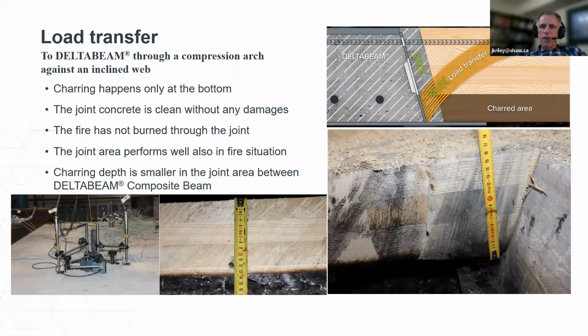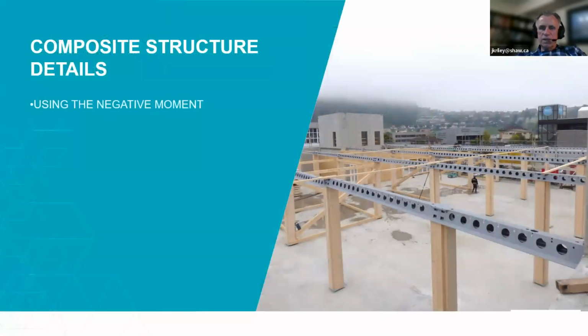Okay, let's move away from fire and let's go back to some of the design notes. So as I mentioned earlier on, we use Gerber connections, and a lot of the connections are done across the tops of the beams, or tops of the columns, not the tops of the beams. Well, actually, top of the beam, come to think of it. So what you see here, it's a simple system. The columns are bolted to the floor or to the deck below or to the footings below here. And you can see the loading for and the fastening point for the next column.